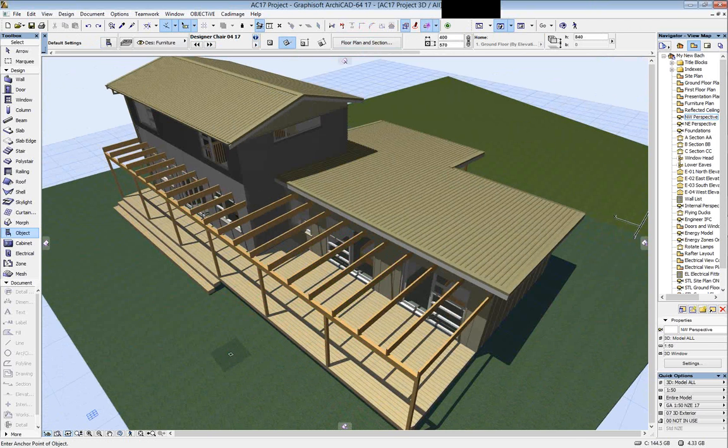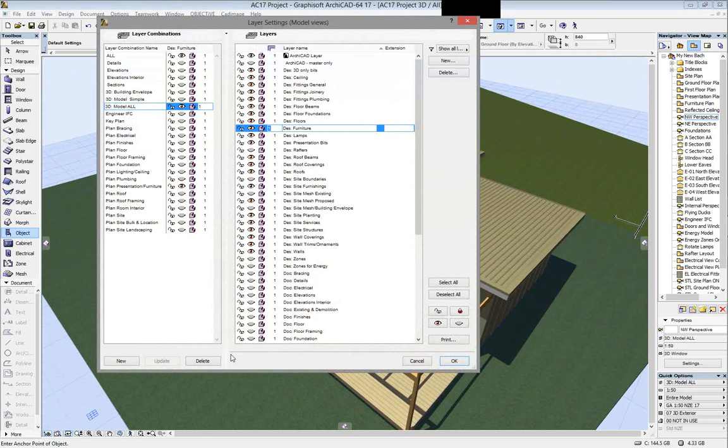So page 29, if you are following along, priority cleanup part 2. Now building elements have automatic priority, we've shown you that, but we can clean up elements in more ways. The main priority we have in ArchiCAD 17 is the same one we had in ArchiCAD 16. It's layer intersections. So if you're not familiar with it, this is the layer intersection number running down here.